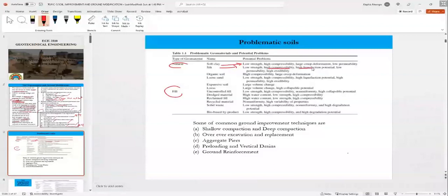As the pore water pressure continues increasing, the effective stress reduces. When the effective stress reaches zero, soil loses its strength completely and begins to flow like a liquid. That can be caused by earthquake. That can be caused by ground shaking due to pile driving.